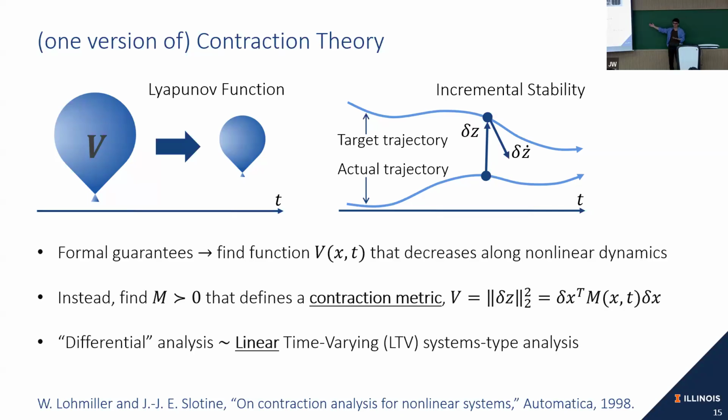So now we are talking about dynamical system. We have x dot equals f of x. And the Lyapunov theory is basically about finding a Lyapunov function V that decreases along the trajectory. So this is a very nonlinear concept in the sense that you use a nonlinear function and you use PDE to find the V.